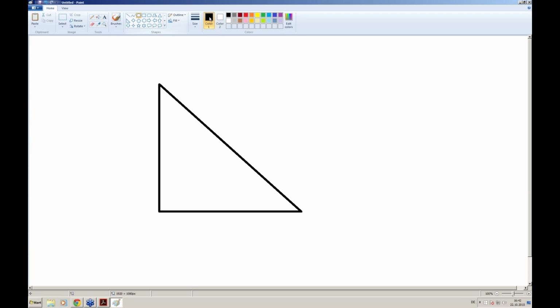And then you have here the nodes and one element, in 2D now, but in reality it is 3D. And a bad mesh, for example when you have a sharp edge or a small feature, can cause the element to get skewed.